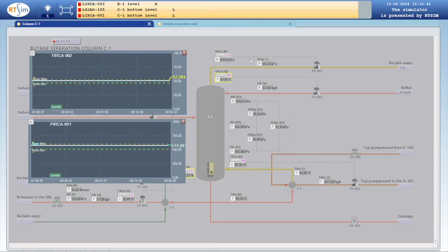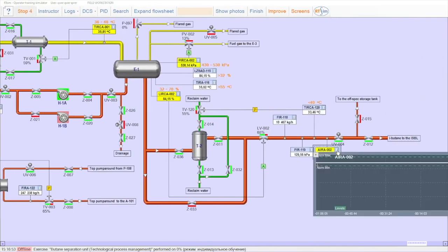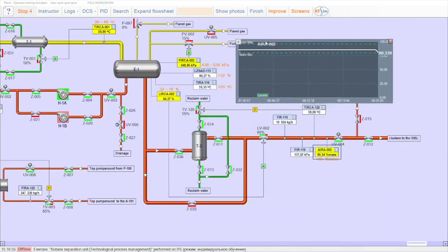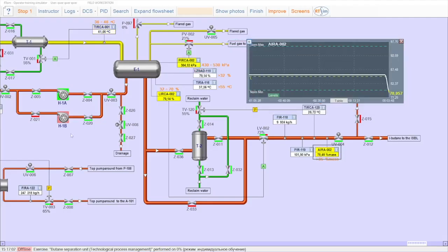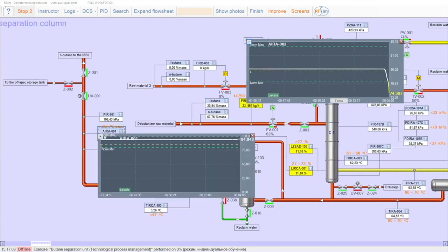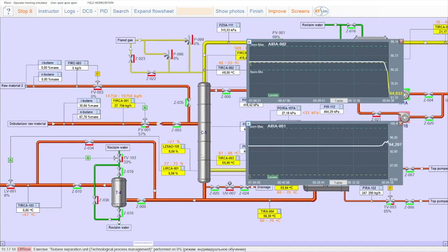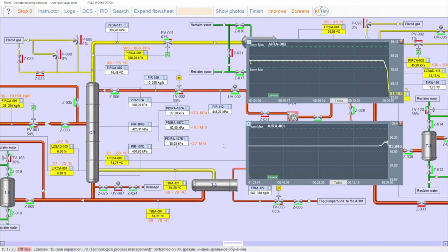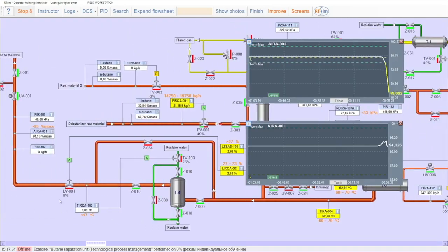To trace the rectification quality, we have to check the isobutane concentration in the product. It is decreasing, but if we take a look at normal butane, it was also increasing, but not for so long. The increase stopped because control valve LV1 was working in automatic mode, it closed and the flow rate of the product was stopped. To summarize briefly, we have seen the dynamics of the process that was emulated by the RTsim simulator.